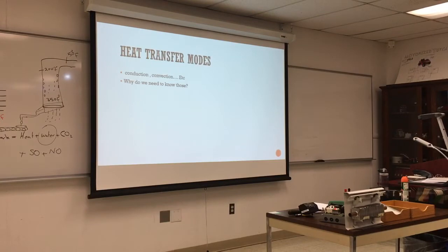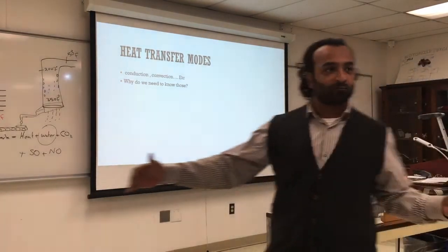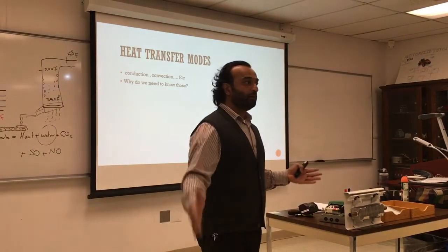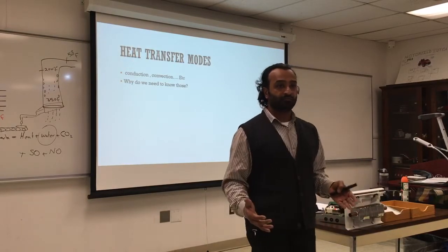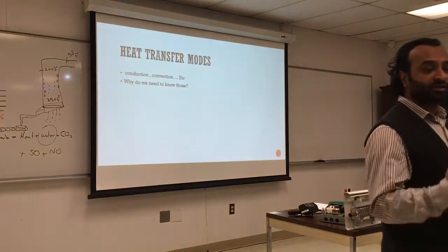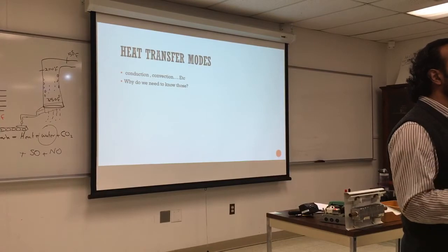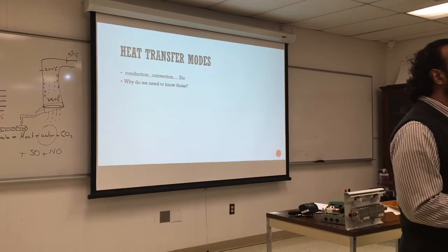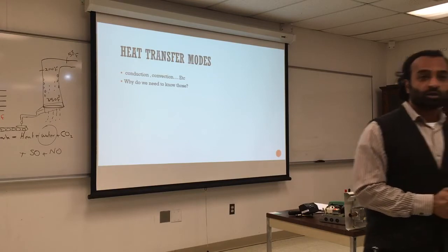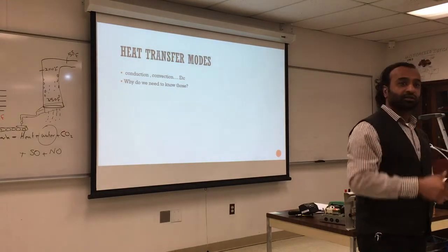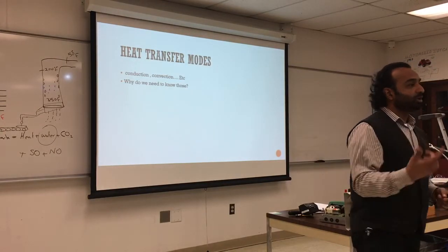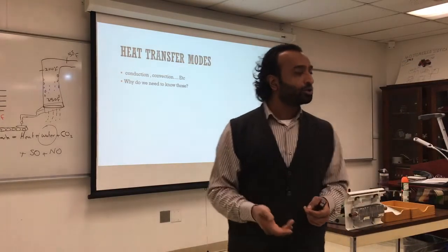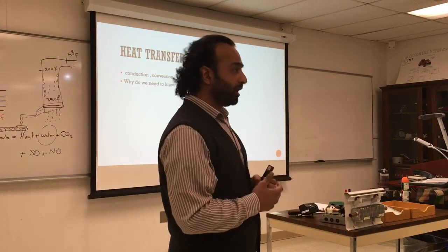They also have something called a convector. A convector is basically, it looks like a small cabinet with a very elaborate radiator, and there's a fan underneath it that will blow air and speed it up. Usually you'll see those in courtrooms or big lecture halls where there's no space for ducts. You need to put ducts, and if you put the radiators on the floor, it's not going to heat properly. So you'll need a convector. They call it convector because it uses forced convection to blow air out.